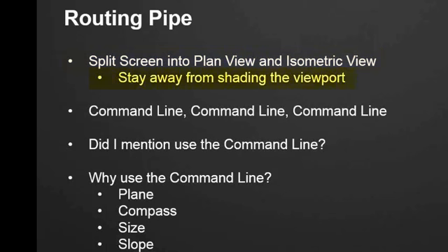I also like to stay away from shading the viewport, giving it a realistic view, a conceptual view, that sort of thing. It tends to bog down your computer and your video card unless you have a pretty high-end system. And even if you do have a high-end system, you can regain some of that processing power to use in the actual routing of your pipe, especially if your files start to grow quite large, if you don't break your levels down into several different divisions. Anything you can do to save your processing and video power will certainly help you in routing pipe.